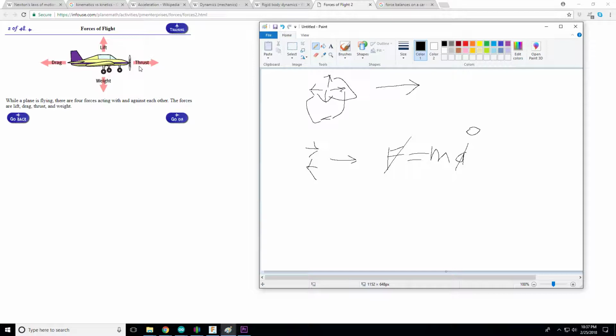And especially on takeoff, because it's not exactly the same as thrust and drag. If your thrust is equal to the drag, that's fine. You'll continue forward at the same velocity. But on takeoff, if your lift and your weight are the same exact force, you will not lift off because your velocity is not changing. You're still on the ground. So on takeoff, you must have drastically more lift than you do weight. And that's all in designing. That's why it's very important here, especially if you want to fly really fast, you want to have ample power to drag.